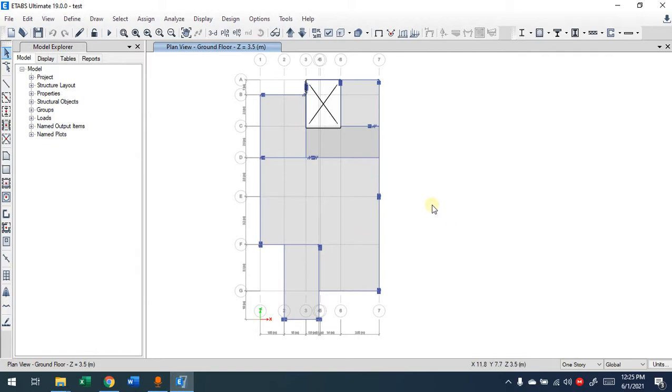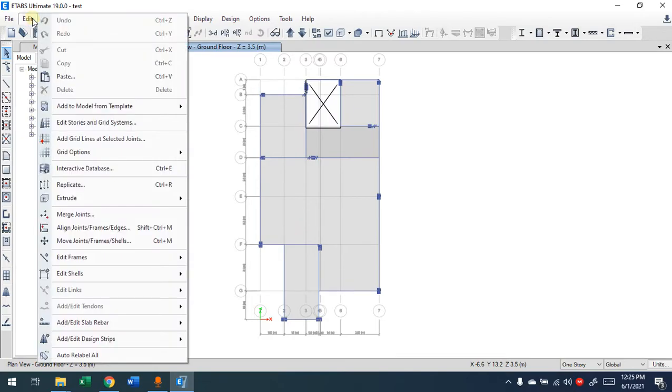For the finite element method, there is a way that we can allow ETABS to define the strips for us, but it will be a bit messy. In the case we have here, we have a lot of grid lines, so it's recommended to draw by hand. I'm going to show you both. I will not make you responsible for the design in a case like this; I always allow you to define it automatically.